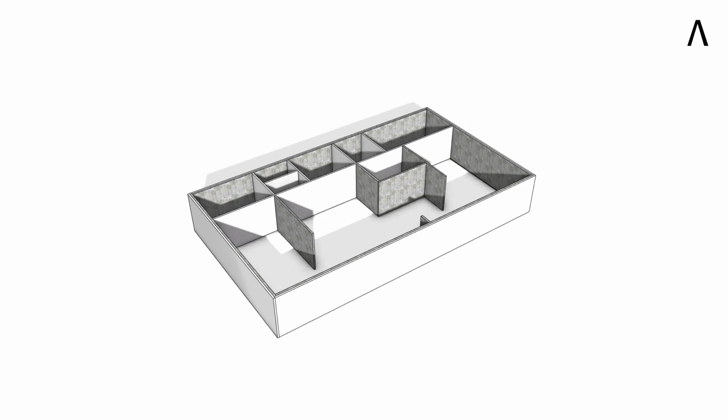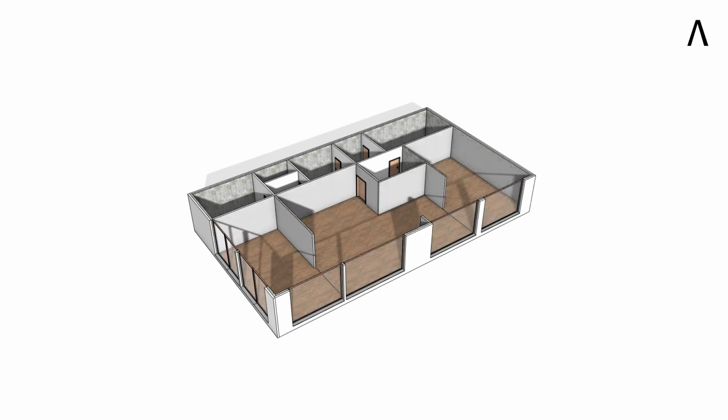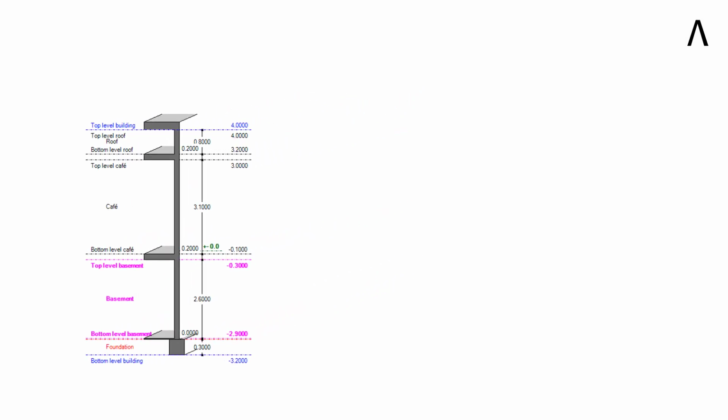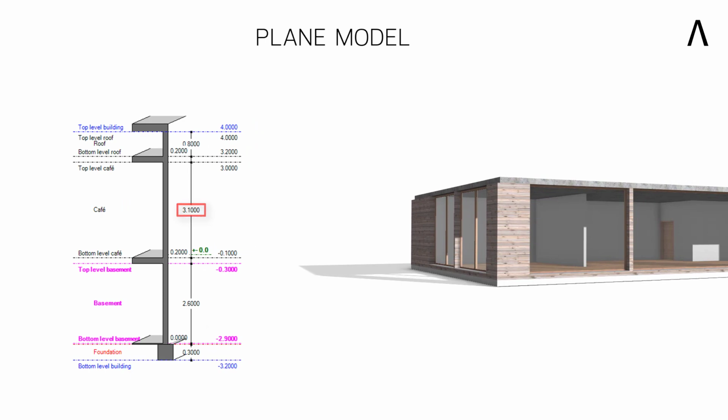We will then create so-called rooms that directly give us the area determination and all finishing surfaces, and will then create a couple of outer dimensions, the slab over the ground floor, and will then deal with our building facade by using the story function. To finish, we will then take a brief look at the floor manager that is responsible for the heights in the model, and then we'll quickly change the story height in the ground floor.